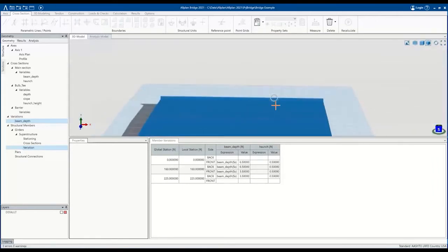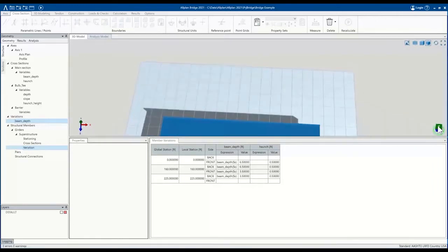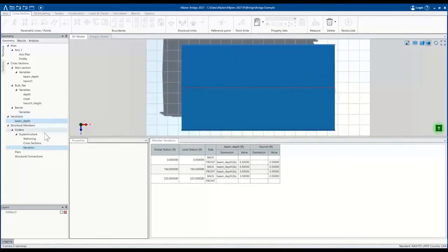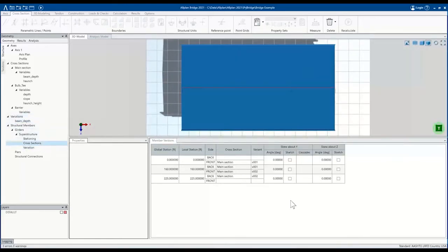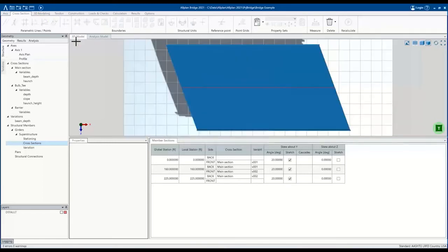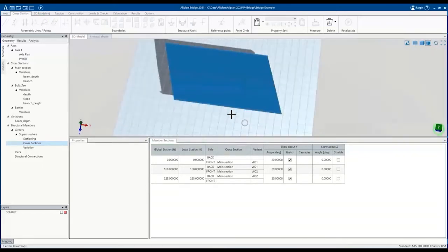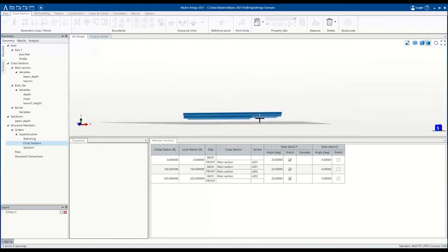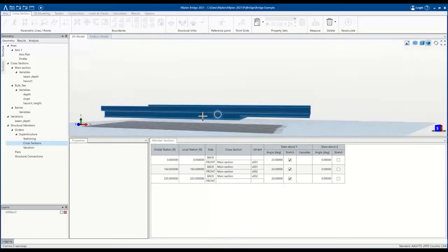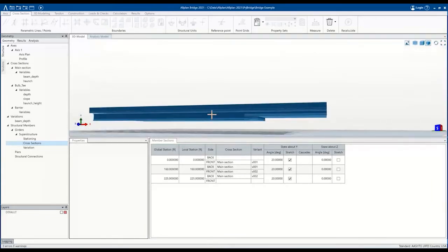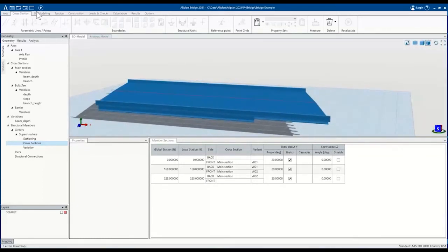If I'm cambering a precast girder, though, I can use just a simple function, a parabolic function, with the narrowest depth at the middle and the deepest at the ends. If I want to do something that's more complex, like say cambering a steel girder, I had the calculations coming out of a spreadsheet somewhere, an analytical software. I can put them in here and interpolate between them using a parabolic or a linear function. And I get all the data that I need. I have the correct geometry. And I get a model that looks right and can be used in a 3D setting to do measurements, to do conflict checking, to check clearances.